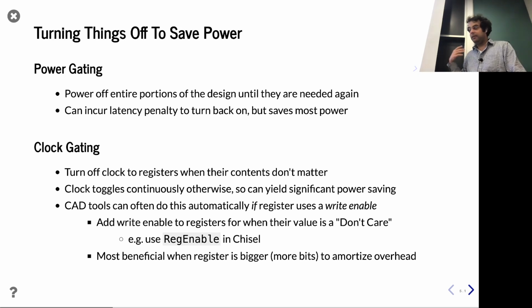What's interesting about this optimization is that it was pioneered in the early 90s. There were tools doing it semi-automatically in the early 2000s. Now in 2023, if you're running an ASIC design flow, tools are extremely good at this. They'll recognize how to attach the right enabled registers to clock gating to turn it off on its own.